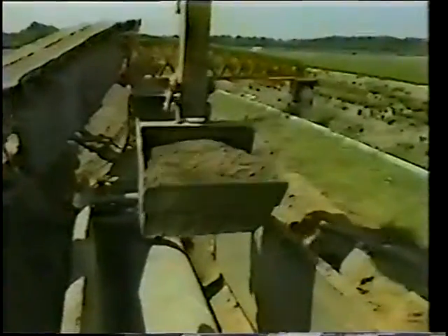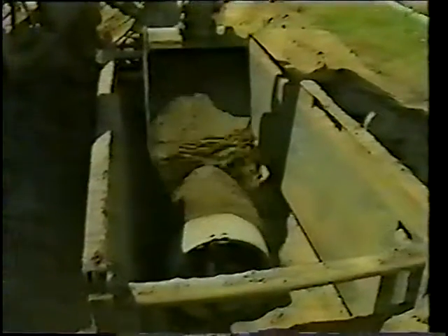Natural mixtures of gravel, sand, clay, or silt from the trench excavation can often provide fair to very good pipe support, depending on the amount of sand and gravel, and be more economical than importing washed, processed gravel.